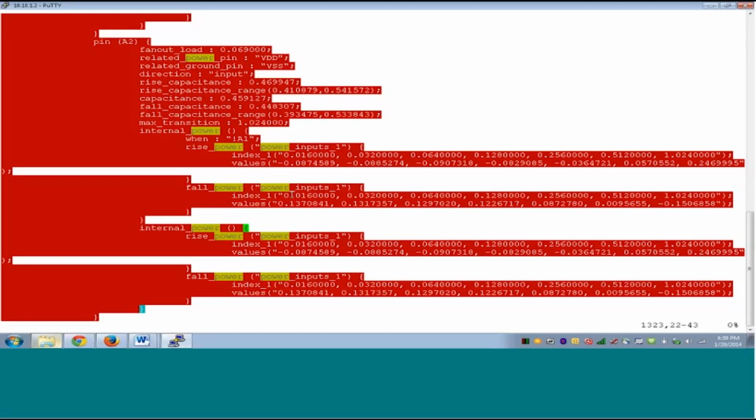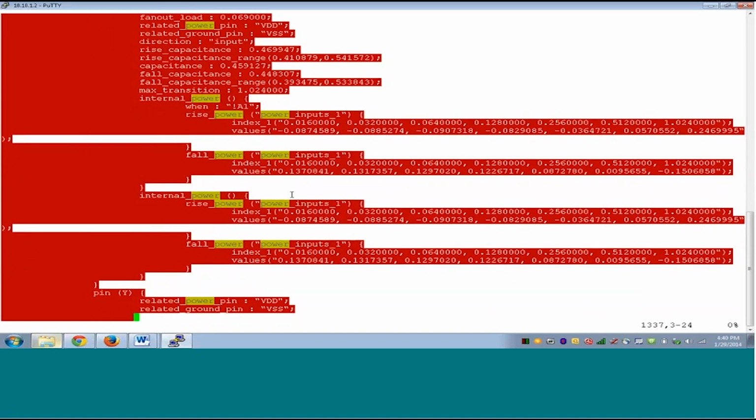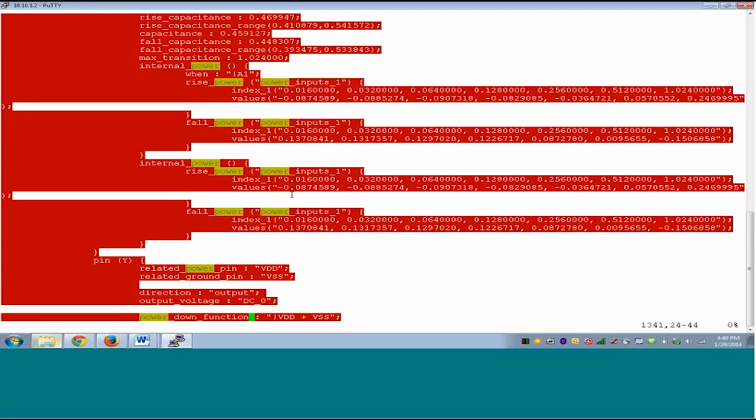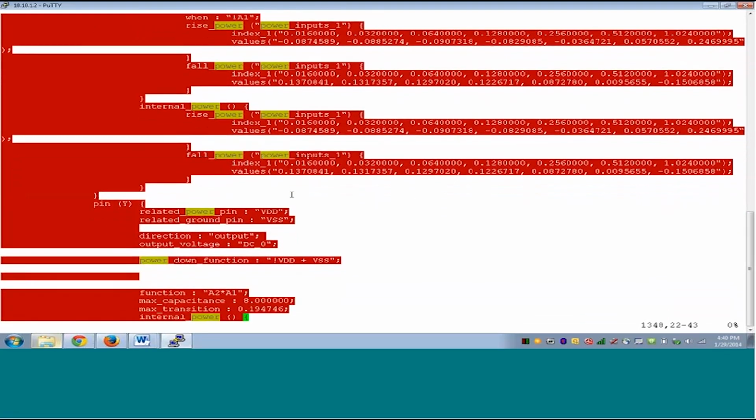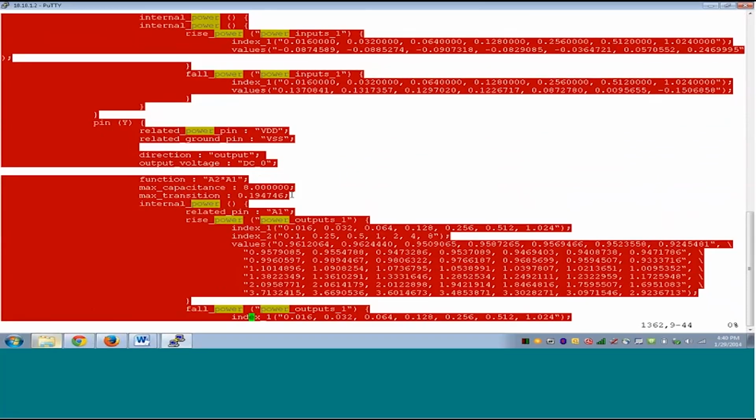Again, for cell leakage power, you might find that cells have just the default value. This default value should be the worst case of all the states that are possible. Not all dot-libs are the same, and not all characterizations are the same. It depends on the team that is doing it and how many resources you have. So the output will have the internal power.